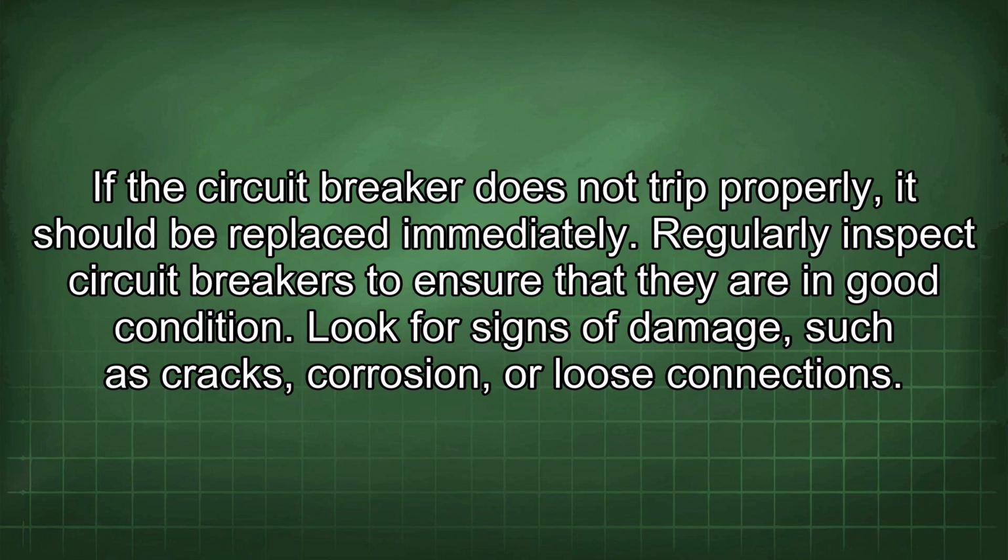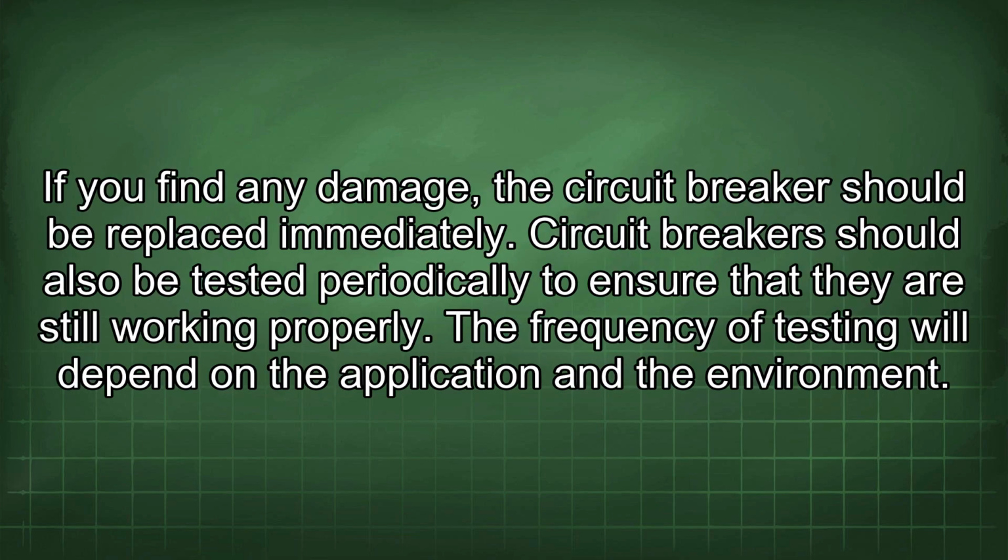Regularly inspect circuit breakers to ensure that they are in good condition. Look for signs of damage, such as cracks, corrosion, or loose connections. If you find any damage, the circuit breaker should be replaced immediately.